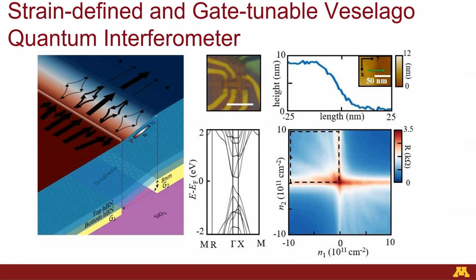The top part of this panel is a contour plot which maps the carrier density distribution in the device. Uniform p-type and n-type doping are found in regions on top of gate 1 and gate 2, while a uniform p-n junction forms in the cavity between the two gates. Two narrow depletion regions are formed along the boundary of the gates, where significant lattice distortion opens a band gap estimated to be on the order of about 100 milli-electron volts based on band structure calculation.